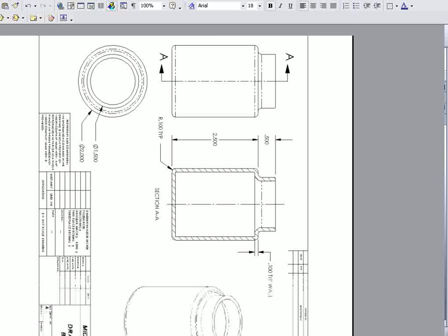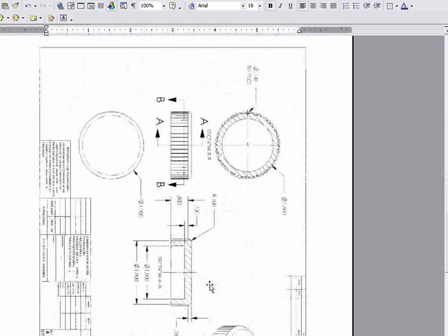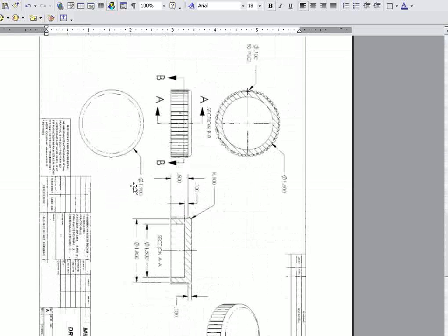And let's look at the drawing for a second. Now in the drawing, what we see here is that there's an overall diameter of 1.9. That's this top face here. And then there's a set of ribs that go all the way around it. There's 50 of them at 100 thousandths in diameter, patterned nicely around there. And what you could see actually is that there's a 1.8 inch diameter ledge there that we want to create. So basically the 1.8 inch diameter is what we'll work first on, and then there's a 1.5 inch diameter hole.